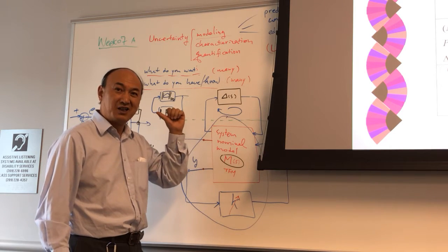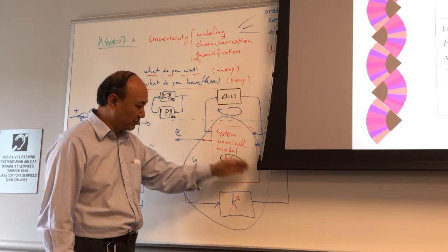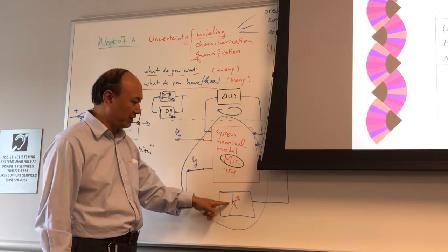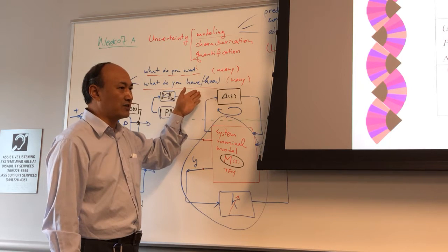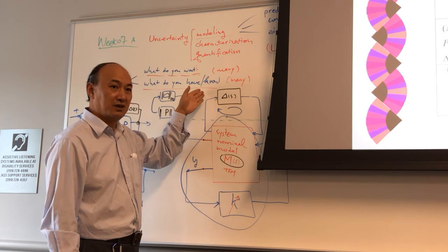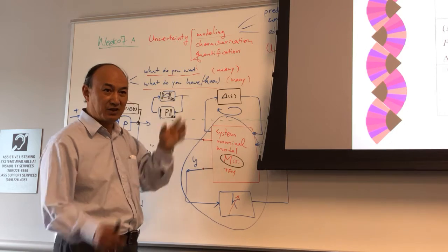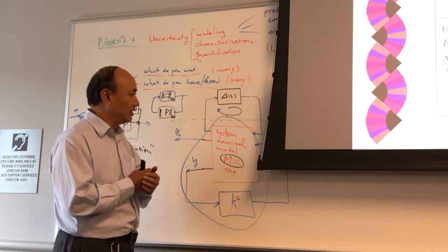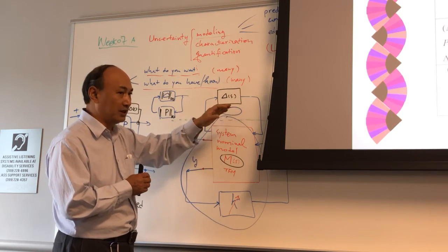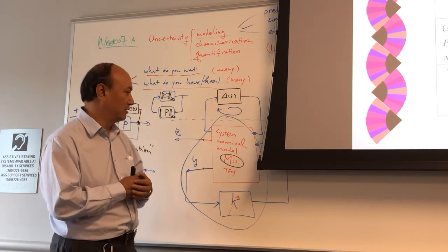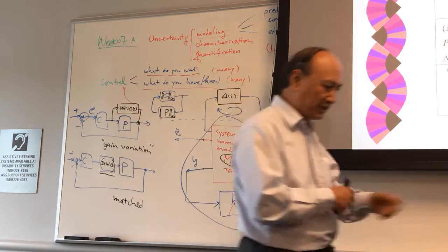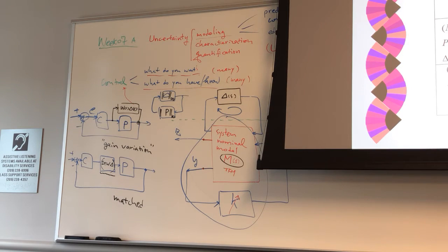So it's NS, the nominal stability design for K. Then check RS, robust stability, for this. So we have learned a trick. The important background is the small gain theorem, and in the MIMO setting, you just be careful about these sensitivity transfer functions.